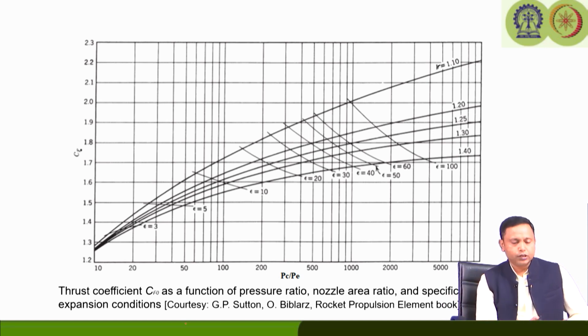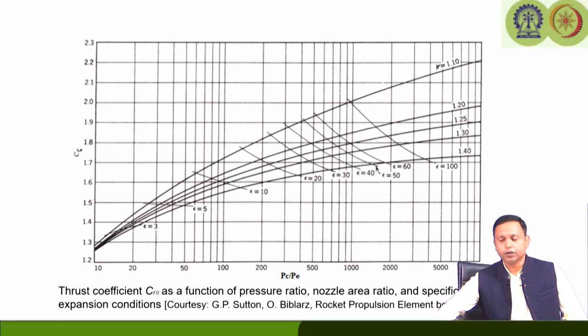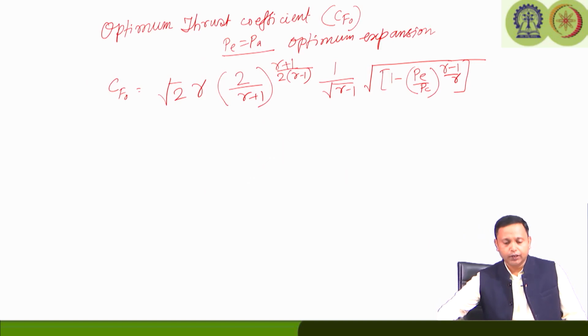Now, after getting all these relations, we can try to combine some of these equations together in order to have some convenience in calculations. We can just look at what we have done here and in the previous lectures, combining the performance parameters. What we understood in the discussions, or even in previous courses, is that the thrust developed by a given propellant would depend on how high a temperature the gas reaches in the combustion chamber, thereby increasing the pressure, and how low the molecular weight of the product gas is.